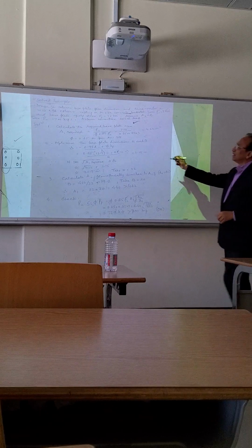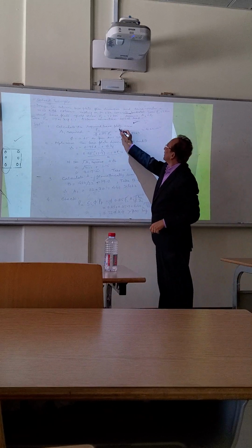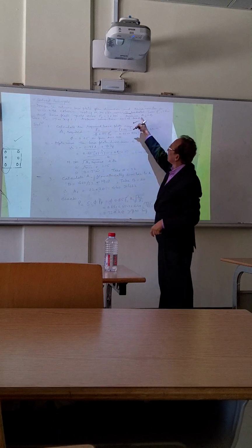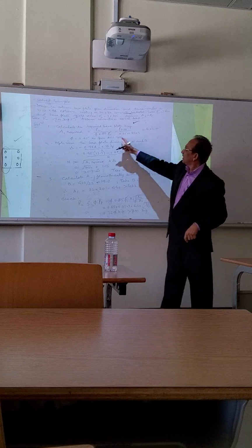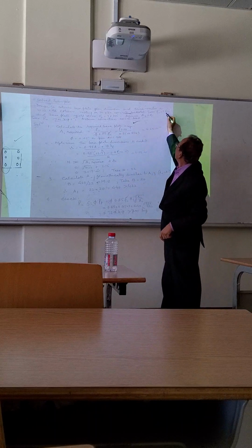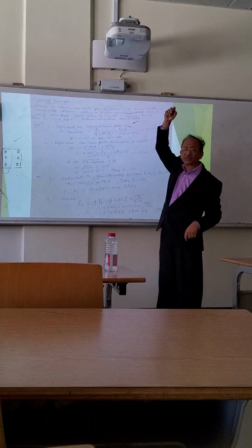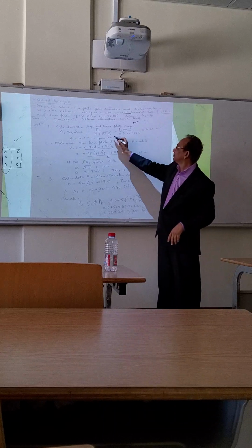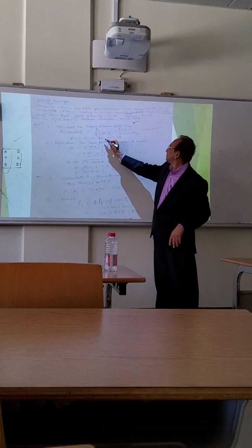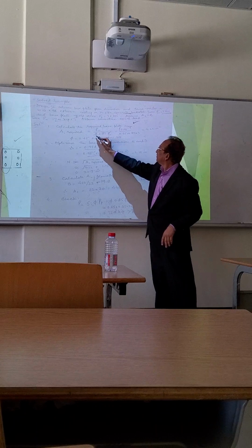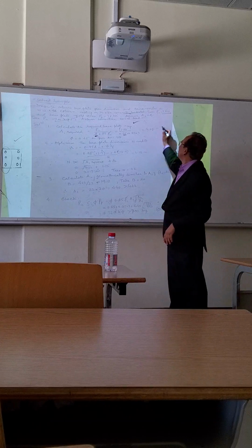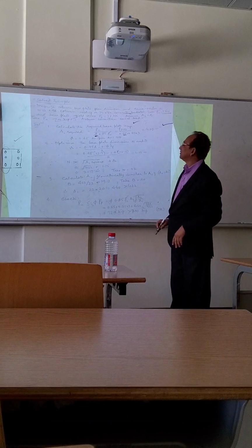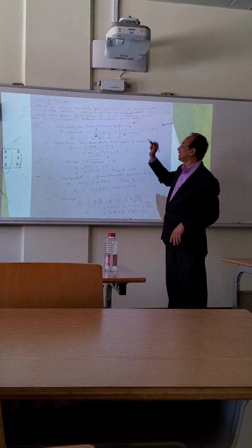Pu is 700, and we substitute f'c as 3 ksi. In some questions it can be 4 ksi. Phi is taken as 0.65 here as per ACI. So 422 square inch comes out to be the A1 required.